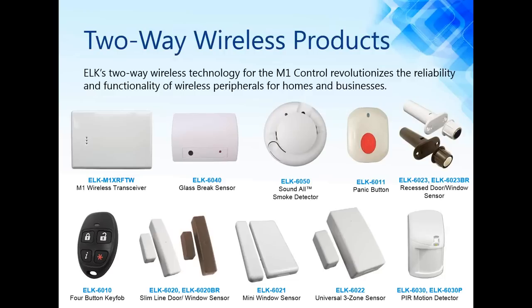We offer our 6020. This is our slimline window door sensor. We offer that in a white and a brown. We offer our ELK 6021, which is our mini window sensor. It's a very small, compact sensor, recommended for vinyl and wood only, not recommended for metal. We have our 6022, which is a universal 3-zone sensor. This is actually 3 zones in one. You can have your built-in reed switch with the external magnet. You can also hardwire 2 additional zones to this sensor, so you get 3 zones out of 1 transmitter. And then we offer a motion detector, the ELK 6030, which is also available in the PET Immune, the 6030P.